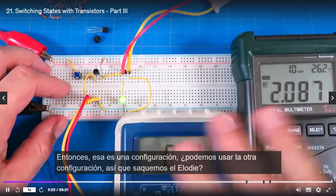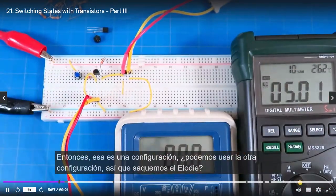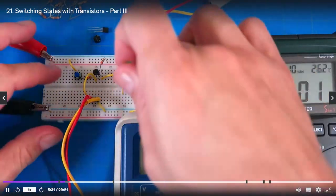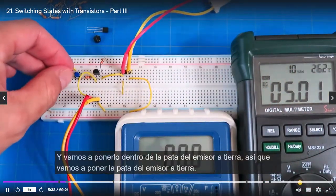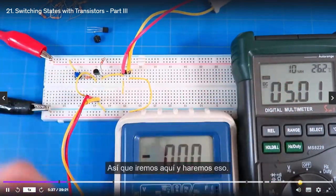All right, so that's one configuration. Can we use the other configuration? So let's pull the LED out. Notice how it goes back up to 5 volts because there's no load on it. And let's put it inside of the emitter leg to ground. So we're going to put it in the emitter leg to ground. So we're going to go right here, we're going to do that.